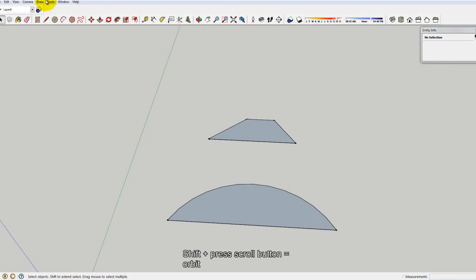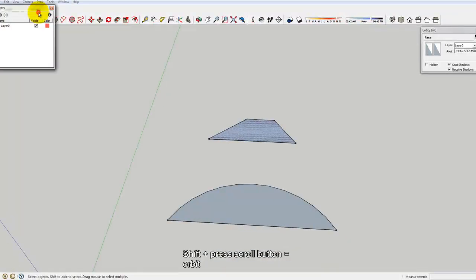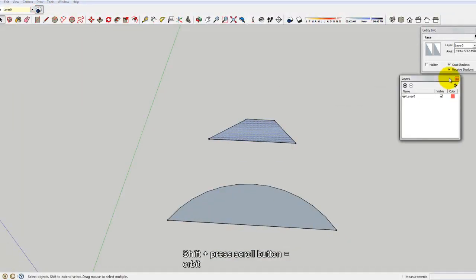And this is the layer, which is necessary because when you're creating a layer, you can choose an object, and then you can select whatever layer you want to assign it to. And what you do now is click on this one. This is the Layers properties dialog box, and this is similar to the layer property panel in AutoCAD.